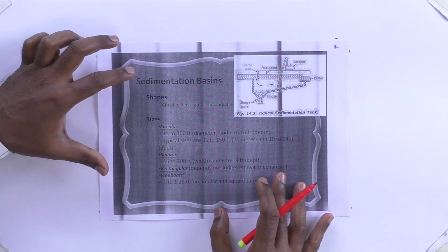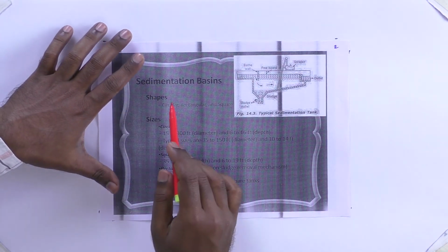But if you need some 99% pure water, then you need to go for the further filtration process. Suppose your expectation is 95% or 99% pure water, then you need to go for membrane filtration. In this membrane filtration only, you can remove some bacteria, some microparticles, all those particles, and you can have ultra pure water. Ultra fine membrane filtration you have to use. So this sedimentation basin only we are going to see.